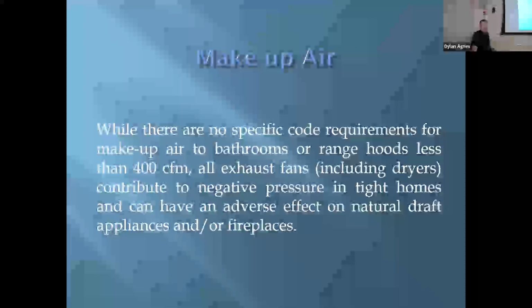And again, there's no specific requirements for bathrooms, laundry rooms, or range hoods less than 400. All fans together contribute to the negative pressure, and they can really have an adverse effect on the natural draft appliances. That one house that I tested up north that had a minus 49, there's no kind of a natural draft appliance that would have worked in that house.